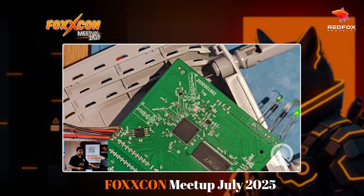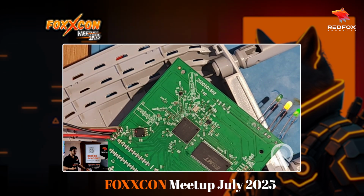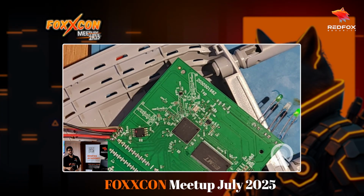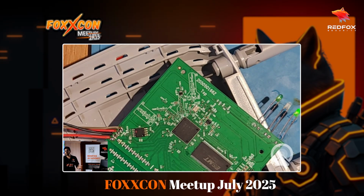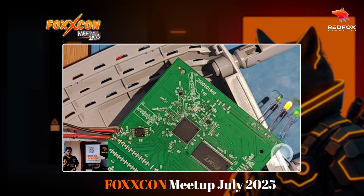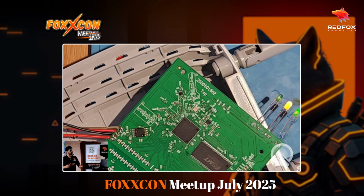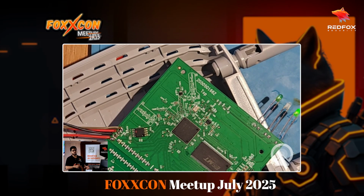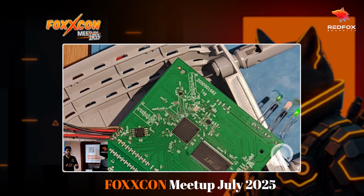And after you have done that, you don't need to connect the VCC cable, which is the power cable, because if you do that, then two voltages will be going to the same thing and it won't make sense. But if it's a very small device, let's say a bulb, and you've taken the Wi-Fi chip off of it and you're trying to get a UART shell on that device, then it will be very easy to just connect up the power pin and connect that to the computer, and that will be able to power that specific device. It's very small, it will not draw that much amperage. That's why it will be fine.